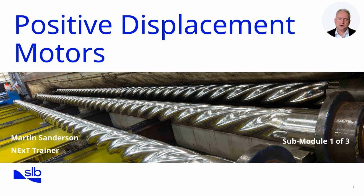This module introduces positive displacement motors. These motors convert hydraulic energy from the drilling fluid into torque at the bit, enabling independent rotation of the bit from the drill string. We will explore their design, applications, selection criteria, and limitations. Understanding PDM fundamentals is essential for efficient, cost-effective, and reliable drilling operations.